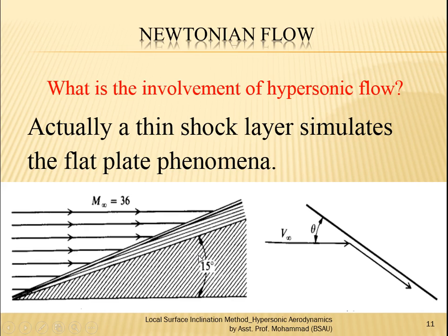So by considering this fact, it looks like this sine squared law will be applicable to the hypersonic flow regime, and it is actually applicable. It becomes a very favorite theorem and equation which gives a quick result. We found that it has very close agreement with the experimental results, and that's why it is in the picture. These are used extensively in hypersonic analysis.